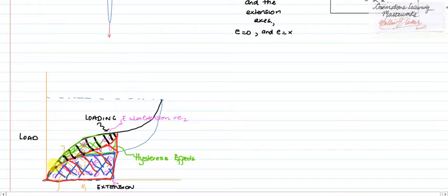If we ignore the hysteresis effects, we'd be assuming that all the energy we stored here, we actually get back. But this little part here will be our losses. If we do our calculations with the assumption that all energy stored is converted into kinetic energy, when in fact this is the energy that actually is converted to kinetic energy, then we'll be overestimating how much energy we have and overestimating the velocity of discharge and so on.